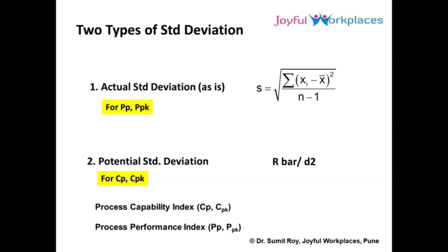Try to take action by using a problem solving methodology. And once you arrive at a fairly reasonable conclusion that your process is really working within the known factors, then you can collect the samples, draw the graph, ensure that it is a normal or near normal distribution, and then calculate your sigma and average. If you calculate the sigma and average by this method, you will be able to conclude whether the process is capable or not.